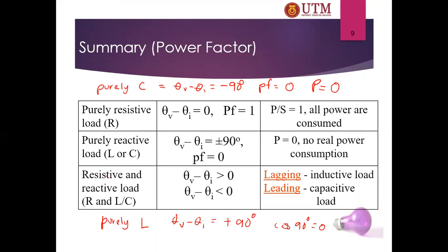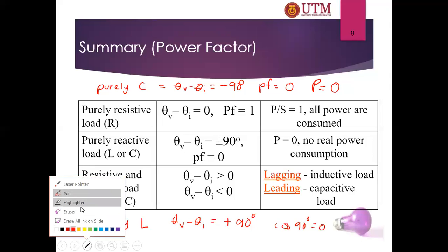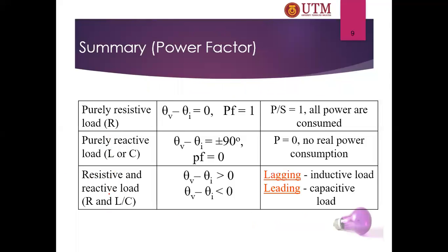Okay, and this is if your circuit contains either resistive load or inductive load. For example, an inductive load, meaning that your circuit contains R connected with L. This one we call an inductive load, so your phase difference will be positive, and your power factor is a lagging power factor.